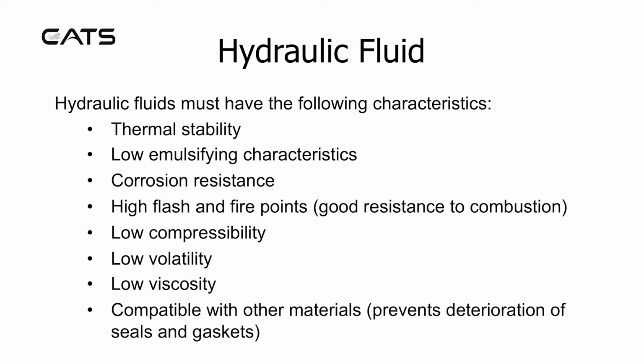Hydraulic fluid properties. Hydraulic fluids must have the following characteristics: good thermal stability, low emulsifying characteristics, corrosion resistance, high flash and fire points, good resistance to combustion, low compressibility, low volatility, low viscosity, and they should be compatible with other materials. This prevents deterioration of seals and gaskets.